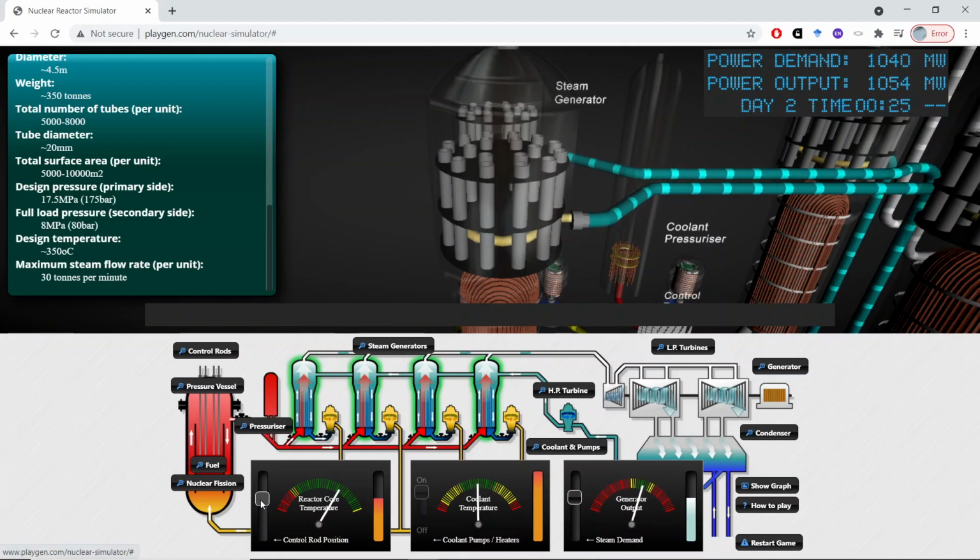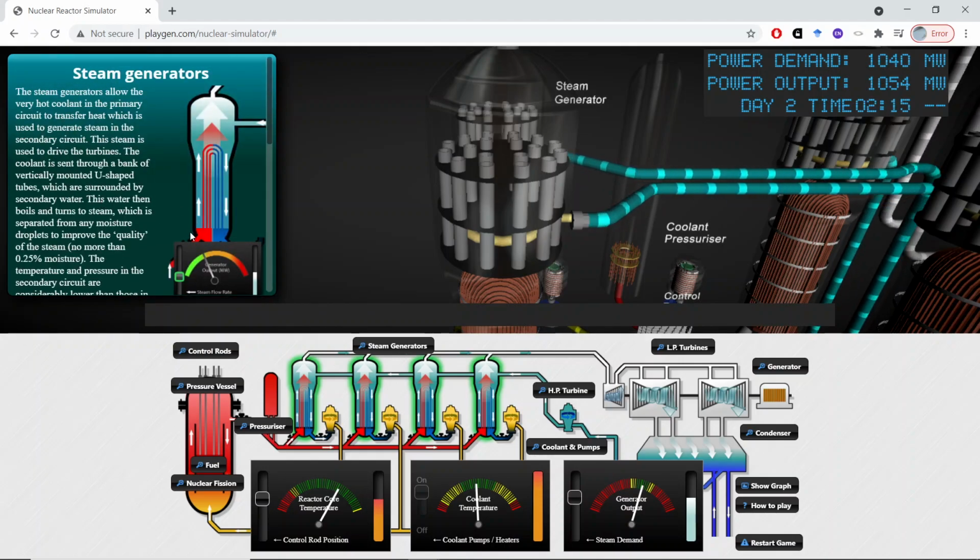Okay, reduce the reactor activity a bit. And I was reading this here. Yeah, this is a typical pressure for a pressurized water reactor. Demand matched. Well done. The working pressure will be around 15 megapascal, so the design of the steam generator is a bit above it. And you see this is the typical Westinghouse design in which you have vertical steam generators.